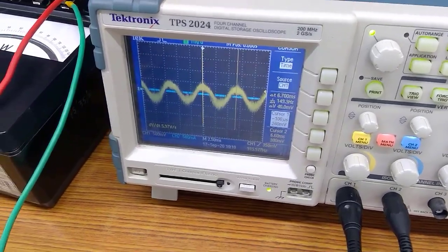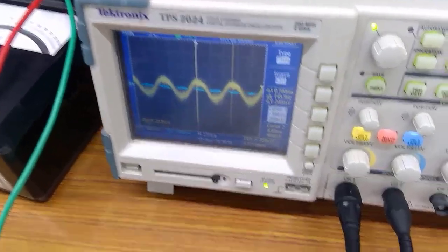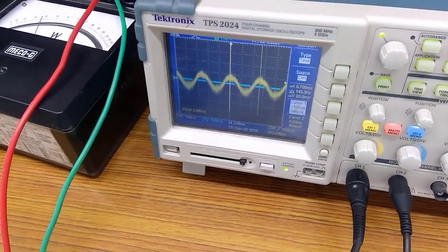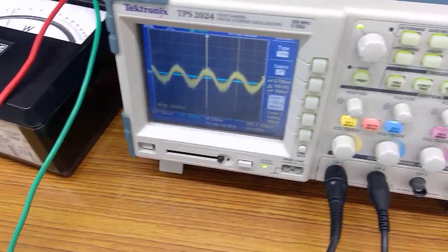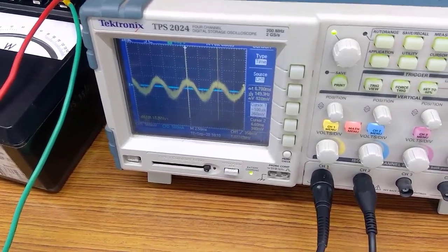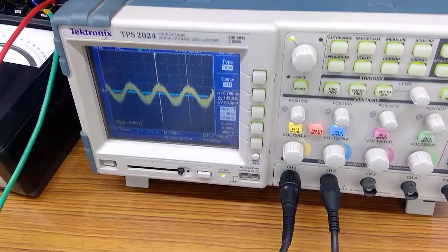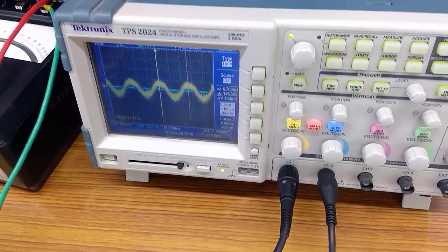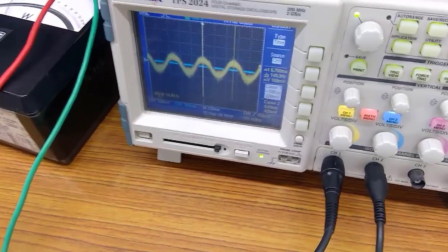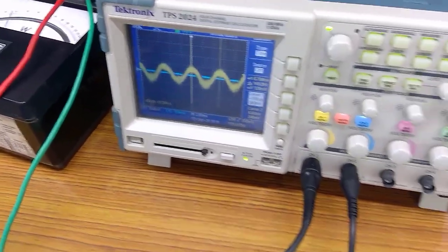That means this voltage signal is actually the third harmonic voltage component. So line voltages have cancelled out, but the third harmonic components in the voltages are co-phasal and do not get cancelled out, and we see the net voltage there, which is the third harmonic component in the voltage.